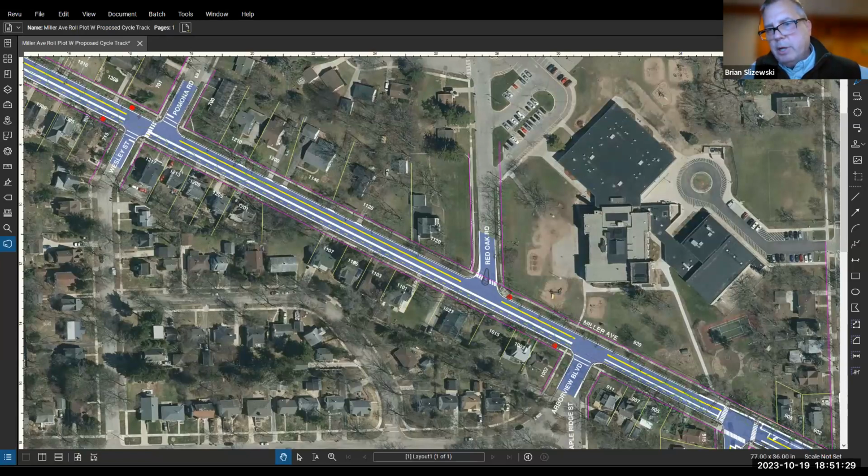And so it provides a transmission purpose for the city, really moving the water through from one side to the other, as much as serving the immediate houses that are connected to it. So old water main, cast iron, 1940s era, 8-inch, maybe some 12-inch or 10-inch. New water main will be all 12-inch ductile iron.